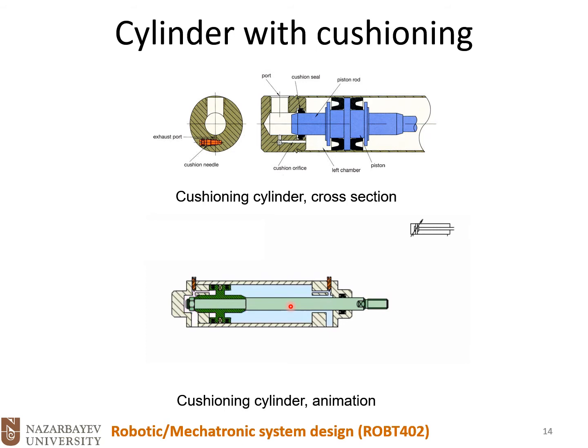So without the cushioning, the piston could bang into the end walls, and of course it creates sound, plus it will decrease the life expectancy of these cylinders. So that's why it's good to have them.